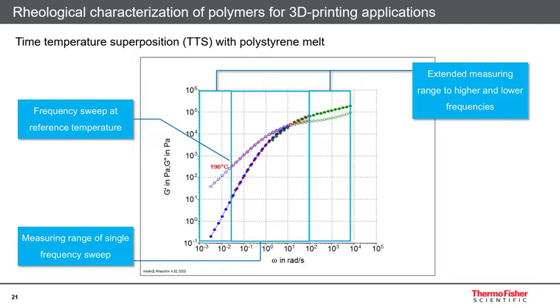The viscoelastic behavior in this range is strongly driven by the molecular weight distribution of the polymer. At the highest frequencies, the sample behaves predominantly elastic, with G' larger than G''. Here, the polymer's behavior is dominated by fast relaxation motion of the shortest polymer chains.